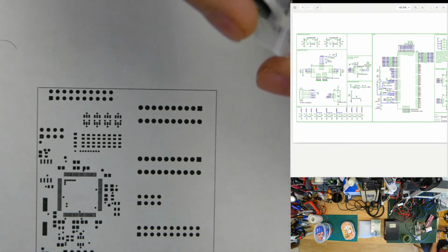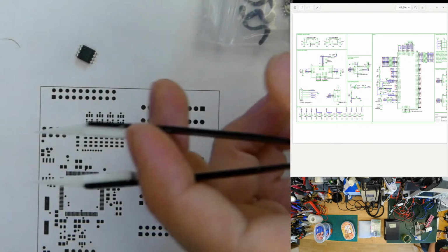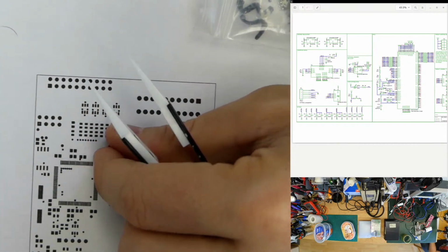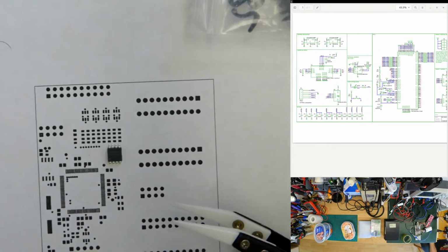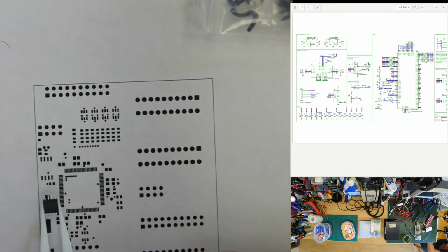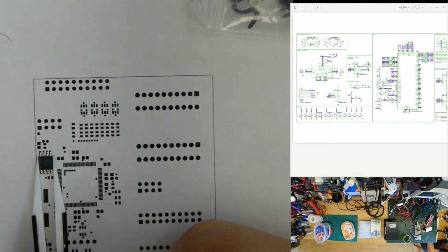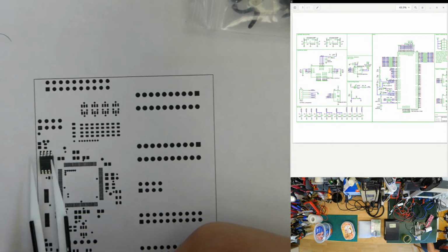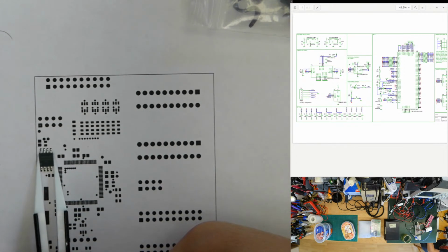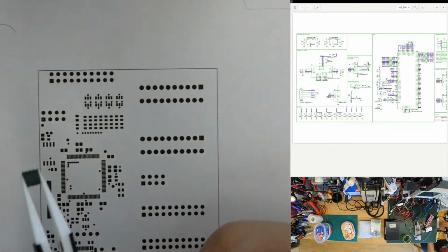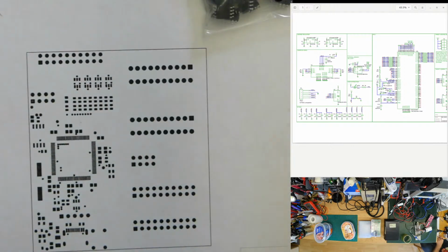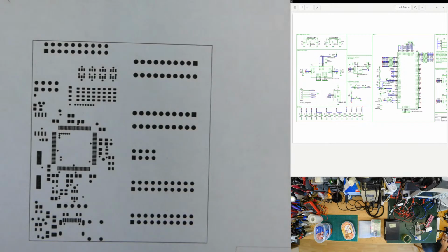Flash is very expensive within the microcontrollers, and you really pay a huge price. You want more flash for the microcontroller, but external flash is not expensive at all. And the part fits. I don't remember, I think this was pin 1, but we don't care, I just want to test if the part fits. The part fits. So with that, all the parts fit, and this step is really important because screwing up footprints is very easy to do, particularly if you don't have the right parts.